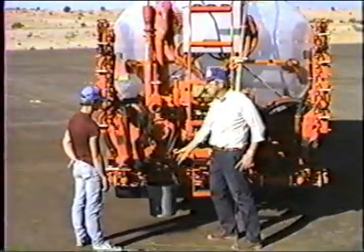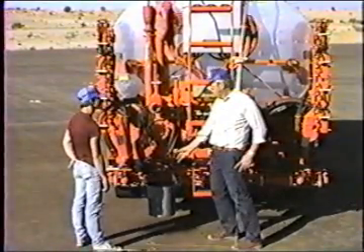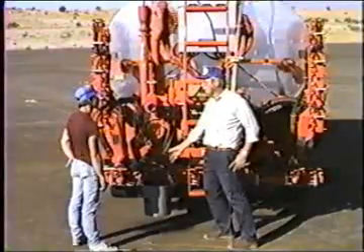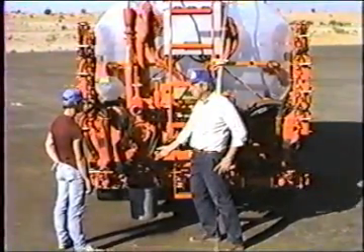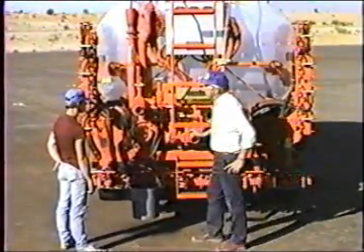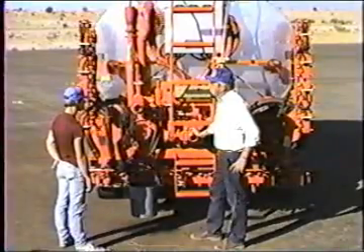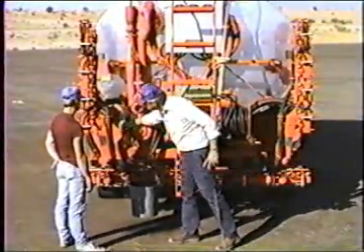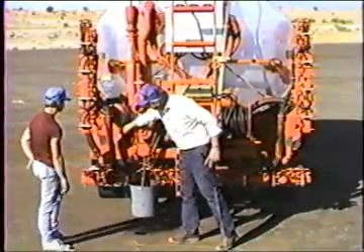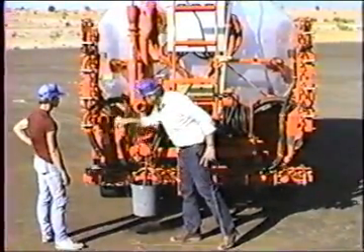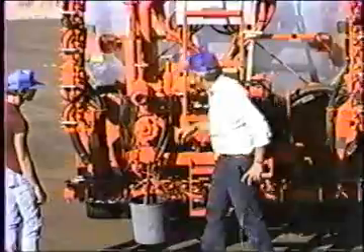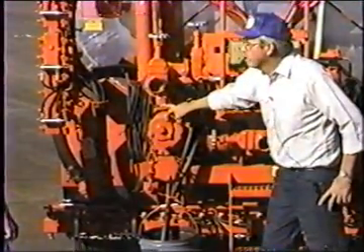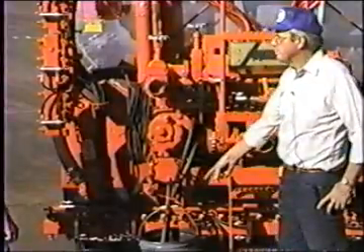The bucket will actually be empty most of the time because it empties the bucket out and it'll burp a little diesel back, and it empties out and it burps some back. That's plenty if we're working with cutbacks or with emulsified asphalts. If we're working with paving grade asphalt, then put some more diesel in the bucket, and you can do that just by taking your washdown hose here, put it in the bucket, turn on the fuel pump, and open this valve that goes to the washdown hose, and just let it fill the bucket up.